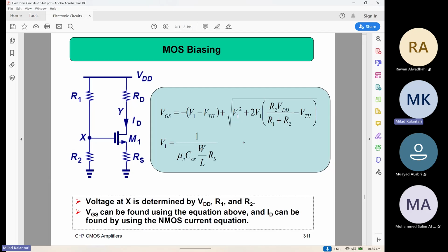The equation for the MOSFET, if you remember, at saturation is 1/2 μn Cox (W/L) (VGS − Vthreshold)². You always need to remember this. For a given transistor, you need to know μn times Cox. W and L are the size of the device, and you can adjust them yourself as a designer.